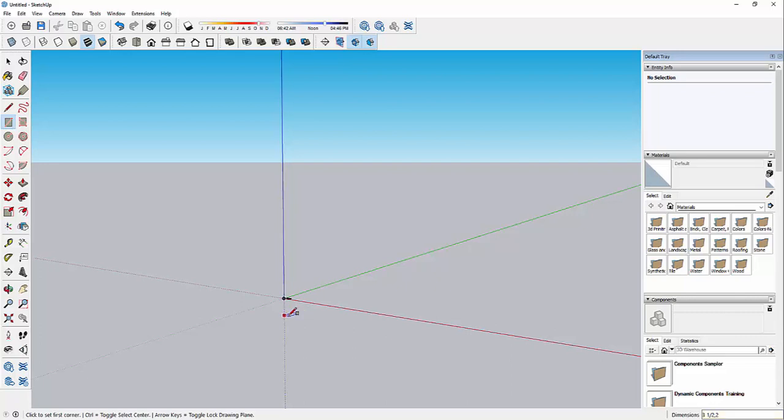So the way you zoom in to see everything, you have a choice here. You can either do the zoom extents tool over here on the left, or you can wheel in with your mouse. So I'm going to put my mouse, let me first clear the command by hitting the element selection tool. Okay, so I'm going to put my mouse over the rectangle that I just drew and then wheel up, and